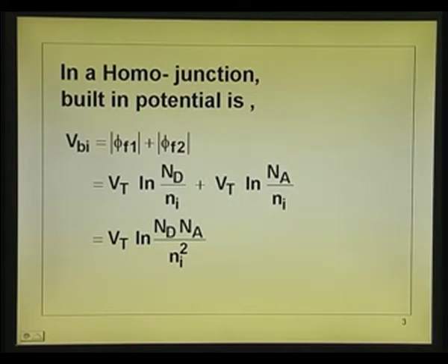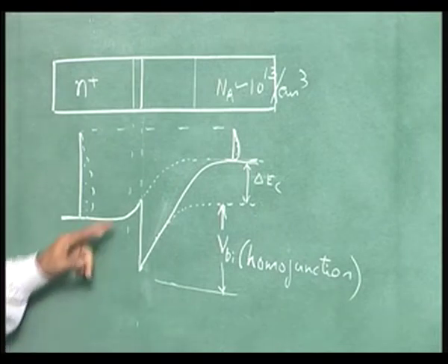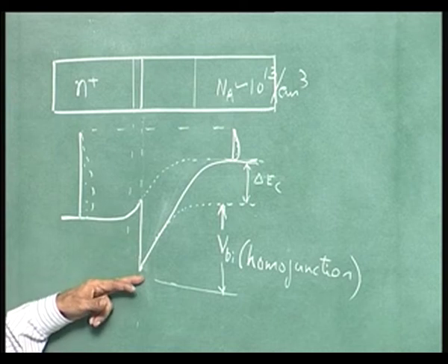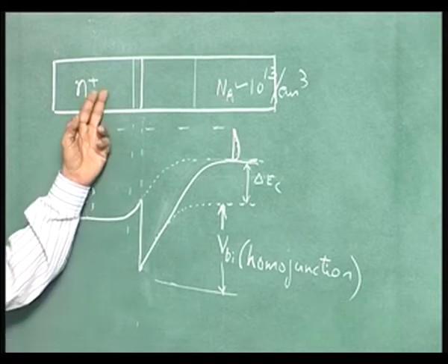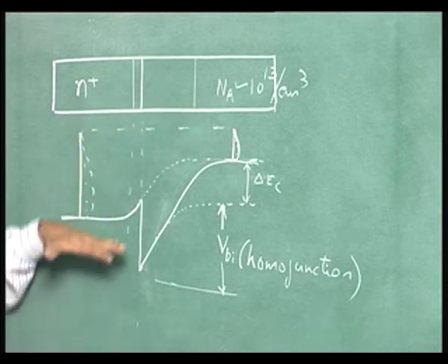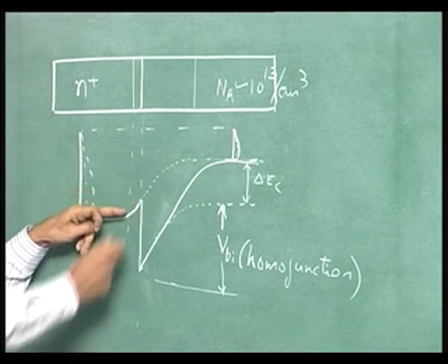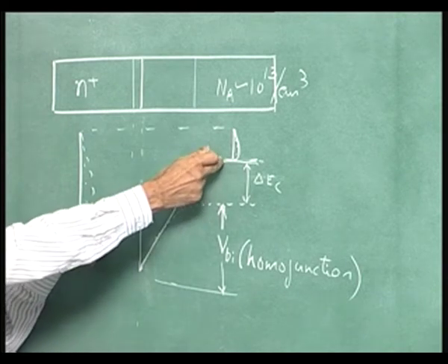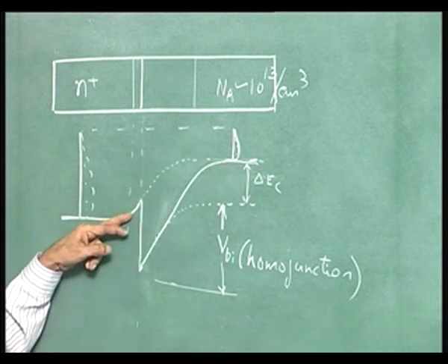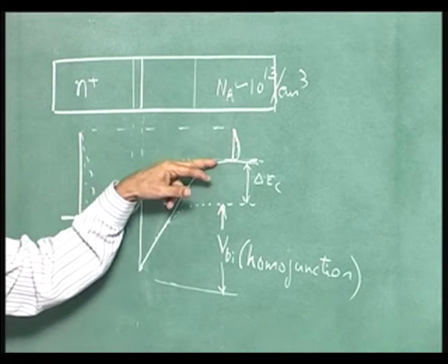Now, let me go back to this particular diagram which we have put in here with a bit more clarity. So, what happens here is, supposing this notch were not present, the Fermi level here is higher in any case. From here to here the electron transfer would have taken place, and finally a potential would have built up there, that is the built-in potential. Let us take the case where the notch is not present, then the built-in potential that you have got here is VBI, which is Vt logarithm of Nd Na by Ni squared, okay.